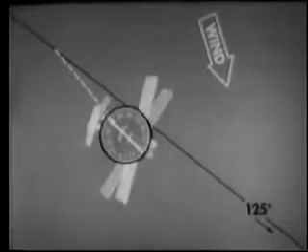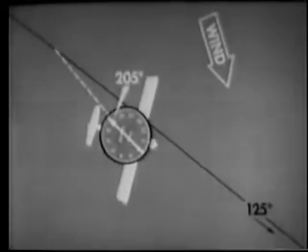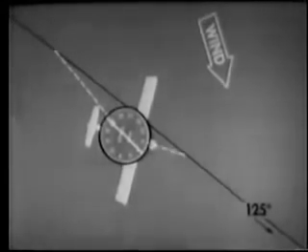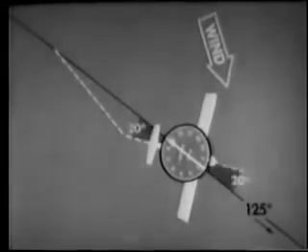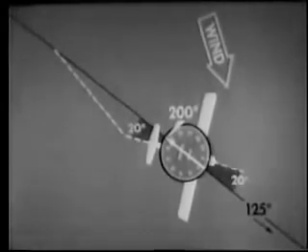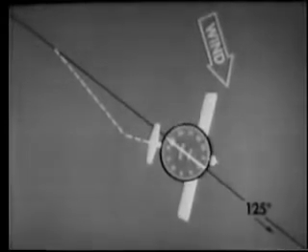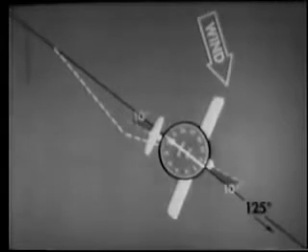As we turn left 20 degrees to return to the track, notice that the ADF needle moves further away from the tail to 205 degrees. As we approach the track, however, the needle will move back toward the tail. When the needle is 20 degrees left of the tail, at 200 degrees, we will be on track. At this point, we turn back 10 degrees. This gives us our first trial correction. We continue tracking as before.